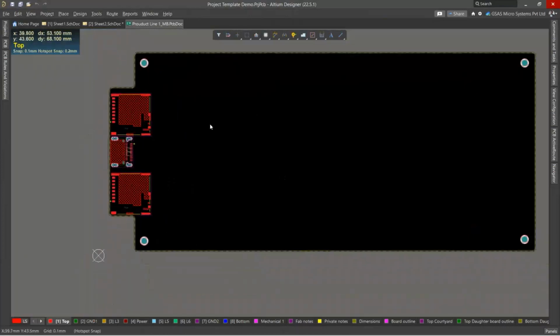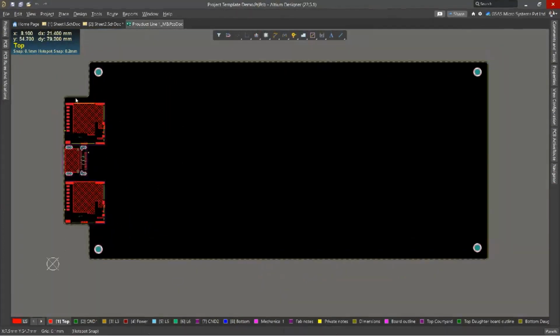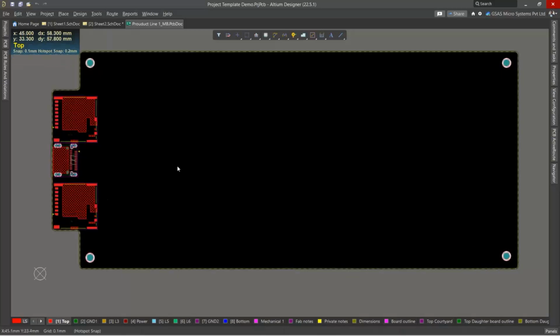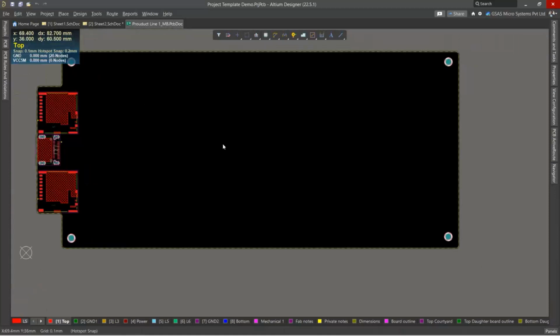The reason why I have added an existing document is that maybe I need to use a particular PCB which will be used for my design, and as the board shape is predefined, it will save my time so that I can directly jump in and do the placement and routing. If I don't have this kind of template, again I have to rely on importing a design file, a DXF file, a STEP file, defining the board shape. If your company has a few standard PCBs that these designs use, then you can create templates for those PCBs, and you can directly add them like this, so that you can save time in designing the board.